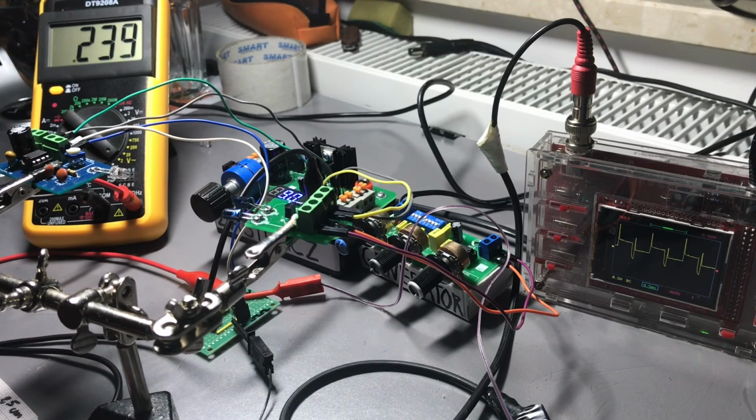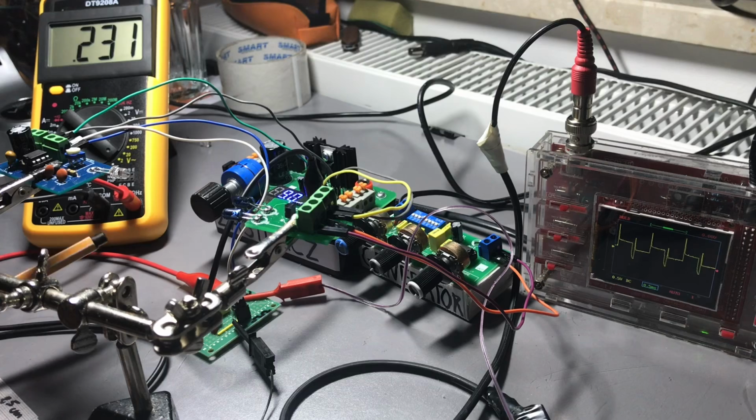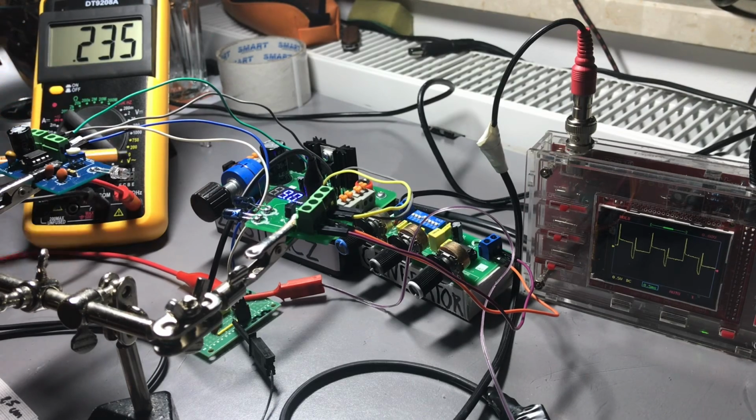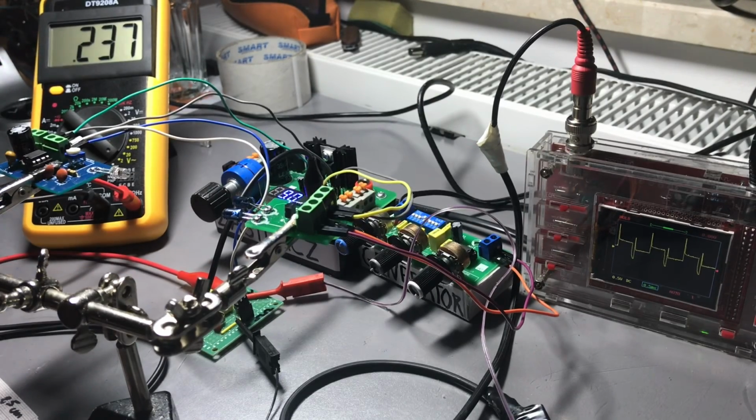The output is so noisy that you will not see any good waveform from it, so I have added this little filter here. The amplifier on this board is a pre-amp stage. It doesn't amplify the signal enough, so you need to get rid of the noise and then amplify it again. On the oscilloscope screen I am displaying the RMS AC voltage that comes out of the receiver, and then, after filtering, this voltage.